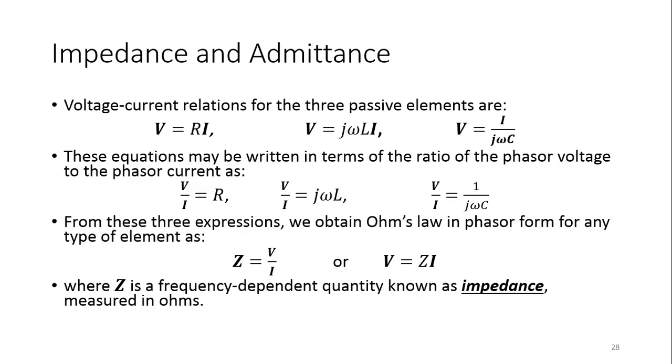Moving on to the next topic, impedance and admittance. We have seen the voltage and current relationships for different circuit elements in our previous lecture. The ratio of voltage and current is actually a resistance. In case of a pure resistive load we call it resistance, but for inductive or capacitive loads we call this term impedance or reactance. If there are only capacitive or inductive parts, then we call them reactance. We are going to see these details in coming slides as well.